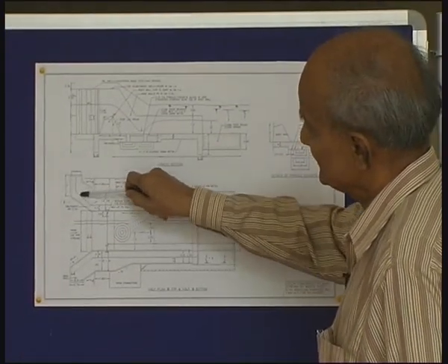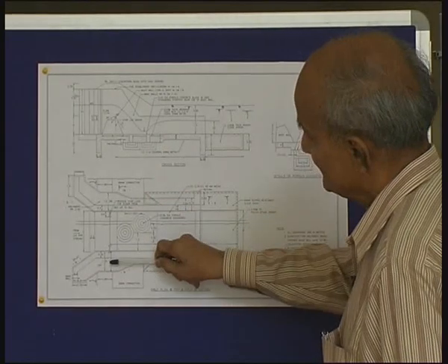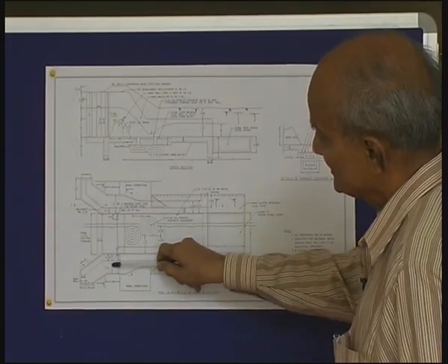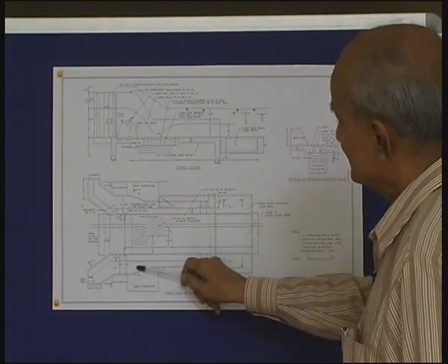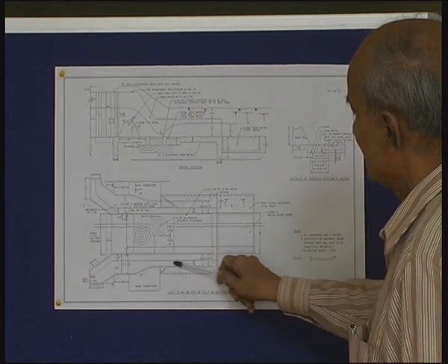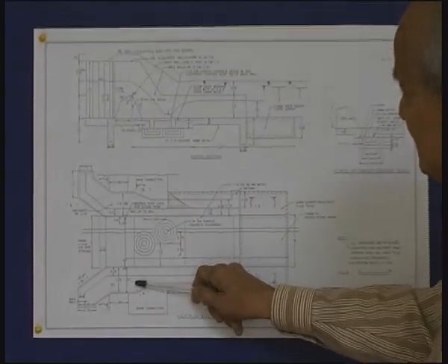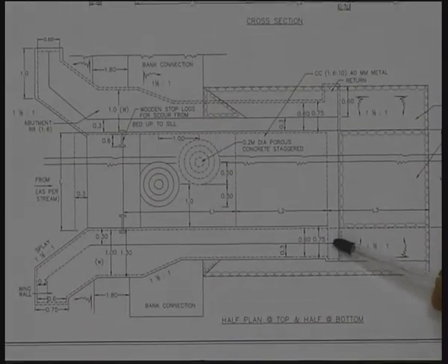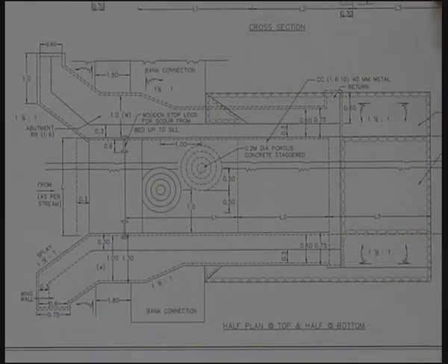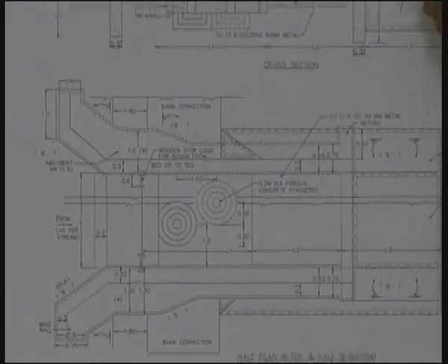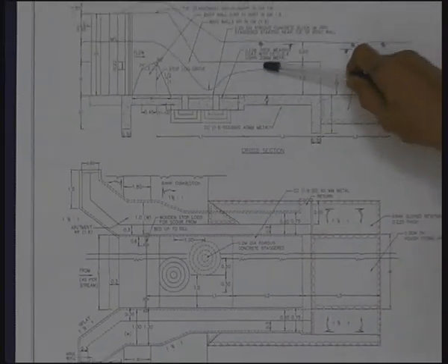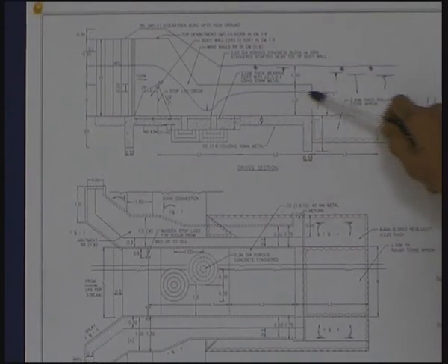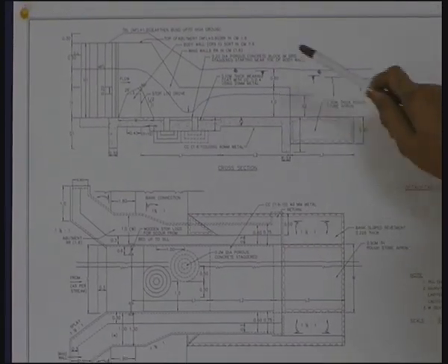So this wing and return is also there on the other side of the stream, and this has got a continuity of wing wall. In continuation of abutment, there is a continuity of wing wall up to a particular distance as shown here, and the height of wing wall should be such that there is a free board when the maximum depth of water passes here.